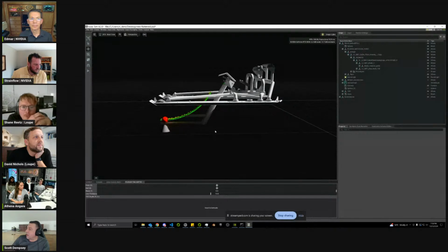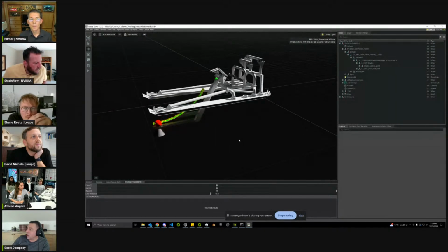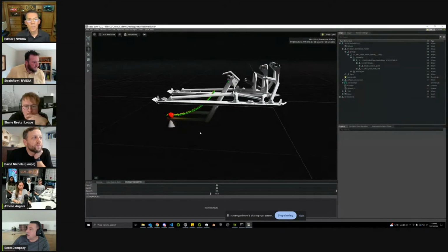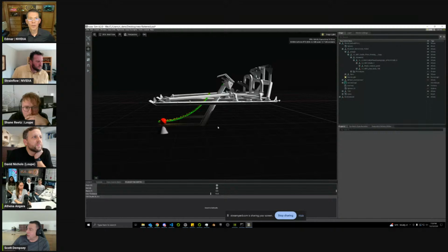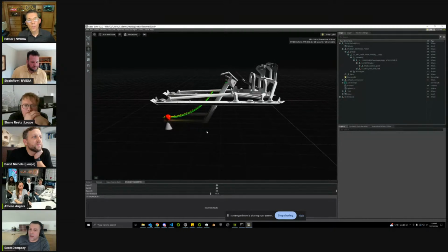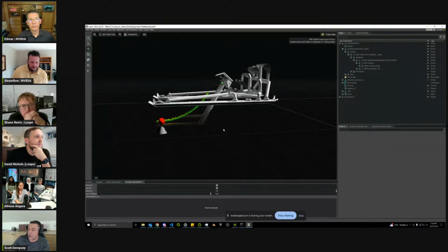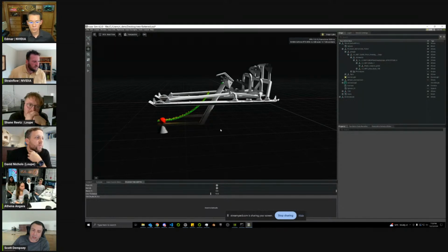Yeah, cool. So basically this is the CAD model of the robot I was showing you. And what I did with this was create a visualization for the burial depth. That's a big thing we need to take into account, because it needs to be deep, but it can't be too deep. If it's too deep, because of the thermal constraints of the cable, we can't dissipate the heat, so it would downrate the cable. So this is one thing we really need to be on point on.